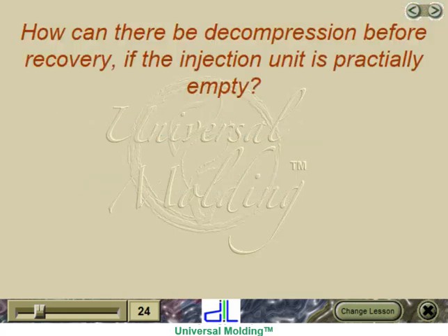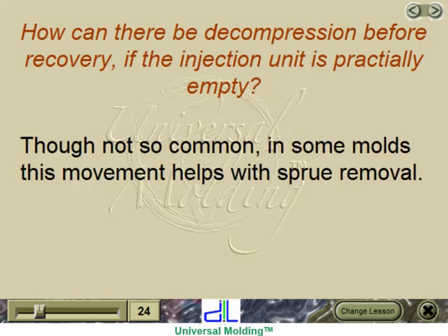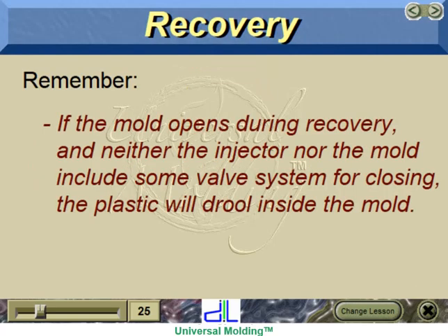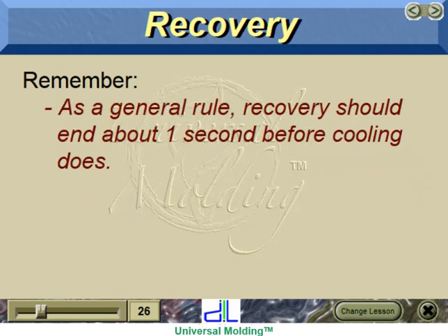How can there be decompression before recovery if the injection unit is practically empty? Though not so common, in some molds this movement helps with sprue removal. Remember, if the mold opens during recovery, and neither the injector nor the mold includes some valve system for closing, the plastic will drool inside the mold. As a general rule, recovery should end about 1 second before cooling does.